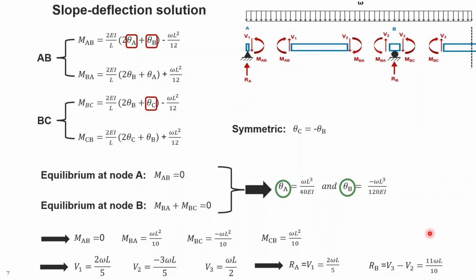So if you have shear forces at elements, you can calculate the support reactions, like RA is equal to V1, because the summation of Fy along all forces here should be 0. So RA is identical to V1, and for example, here you can write summation of Fy equal to 0, which gives you RB plus V2 will be equal to V3. And for this part, the omega doesn't play any role, since you have just cut the element at an epsilon, very close proximity to the support.